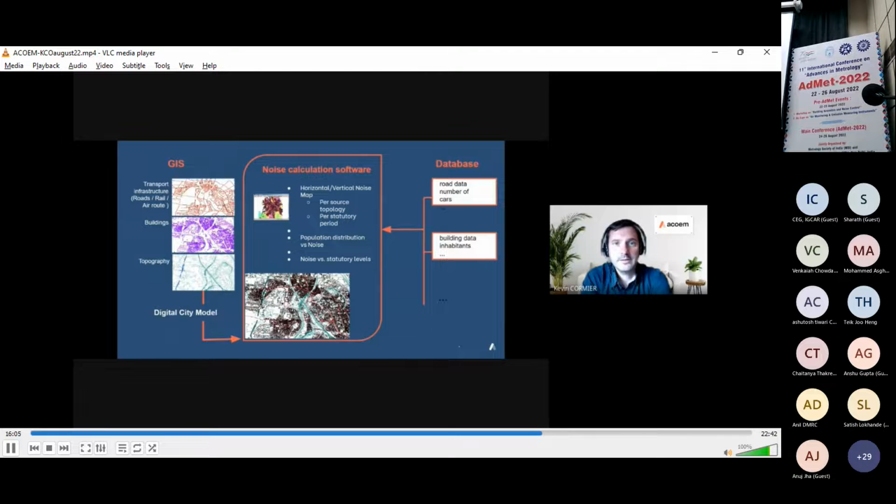A noise map is not the result of on-site measurements, but of computer modeling carried out using data descriptive of the topography, so the relief, the buildings, and other obstacles, and noise source, in particular, data flow from transport infrastructure, speed, a ratio of heavy vehicle, road surface, rail characteristics, etc. This data has to be collected from multiple stakeholders.